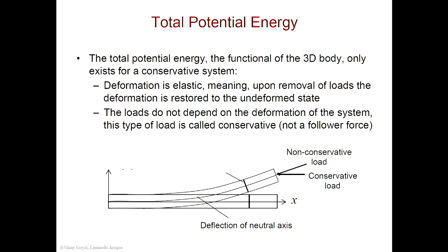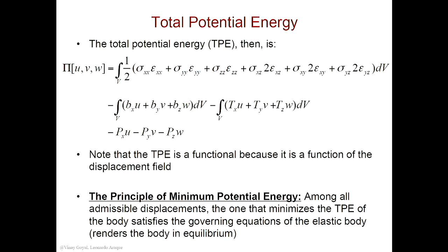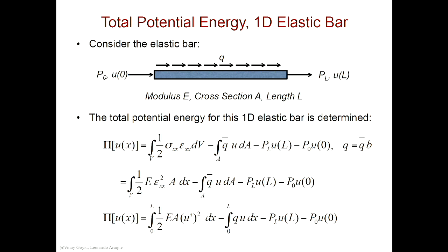All right. So let's apply what we're learning to a 1D elastic bar. In the 1D case, we don't have other stresses acting on this elastic bar, just the stress acting along the bar. And so for that reason, all the other terms I had earlier, I had 6 terms right here, 1, 2, 3, 4, 5, 6, we'll just skip those because we don't have these other strains acting on this elastic bar. We only have loads applied along the length of the bar.